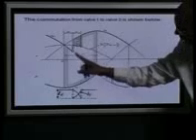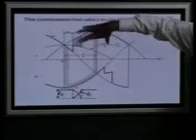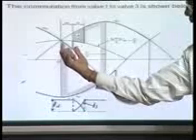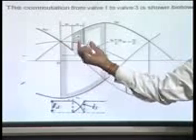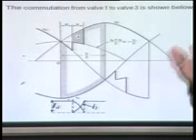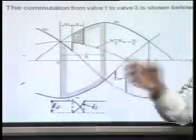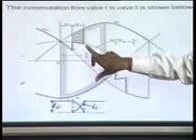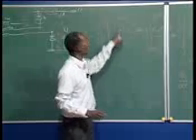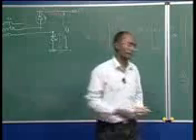So I am just starting for this pulse here up to this portion. This is again 60 degrees. You can start from here also, then you have to take this portion, then this portion, then this remaining portion, and that is again three different components you are adding. Why am I taking three components? Because the voltages during this period are different. So here I change from 0 to alpha plus u, and then from alpha plus u it is again 60 minus u, that is what we are getting.